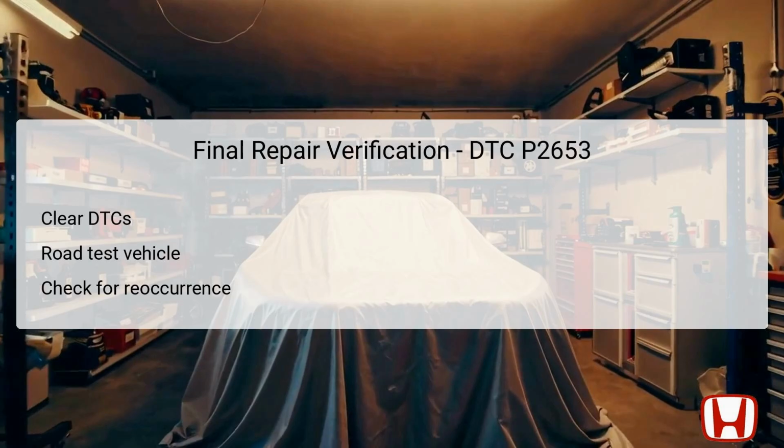During the drive, pay close attention to any symptoms that might indicate ongoing issues, such as the check engine light illuminating again. After the road test, check the diagnostic system for any reoccurrence of DTC P2653. If the problem does not return and the system operates normally, the repair can be confirmed as successful.